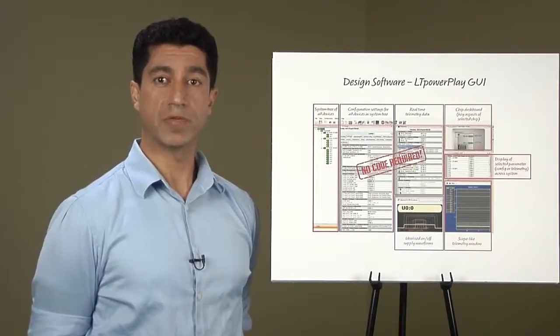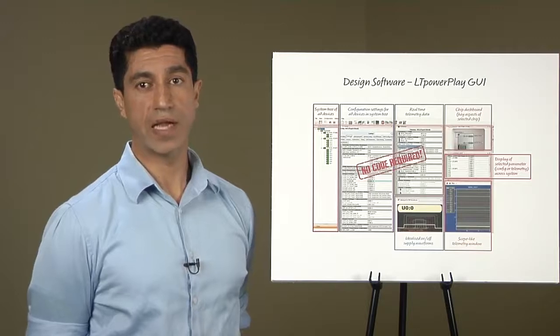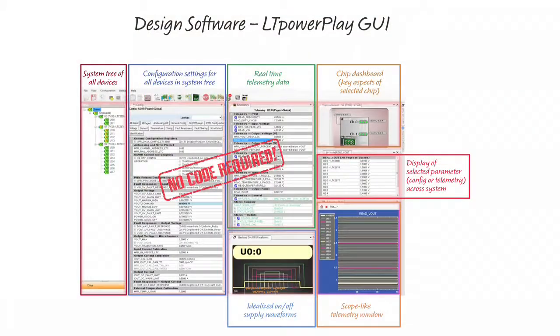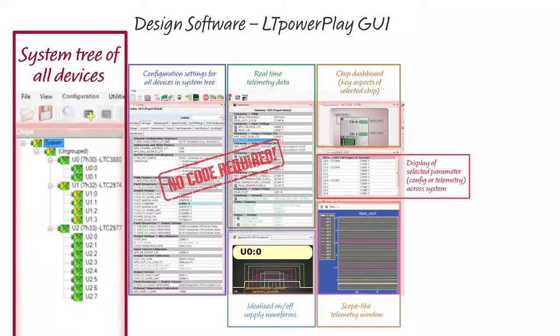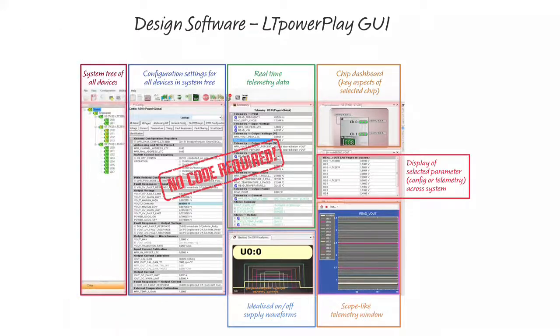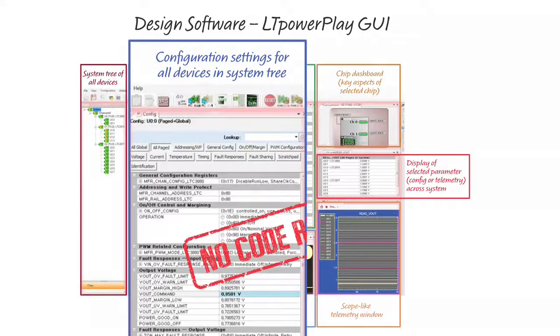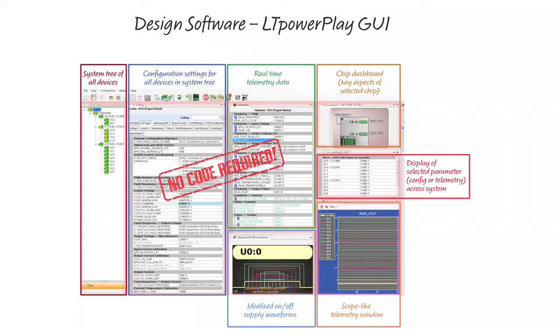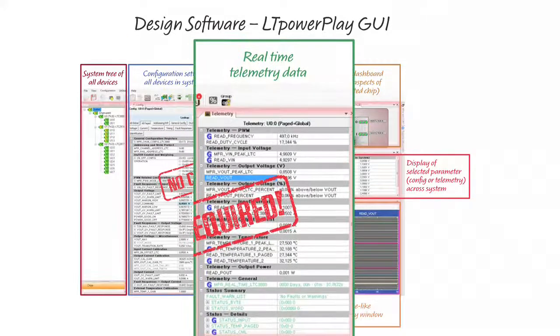Digital power system management products are configured and monitored via a two-wire PMBus interface and open I2C-based digital interface protocol. This enables seamless integration with existing embedded systems and architectures, board mount controllers, BMCs, and intelligent platform management interface, IPMI functions.